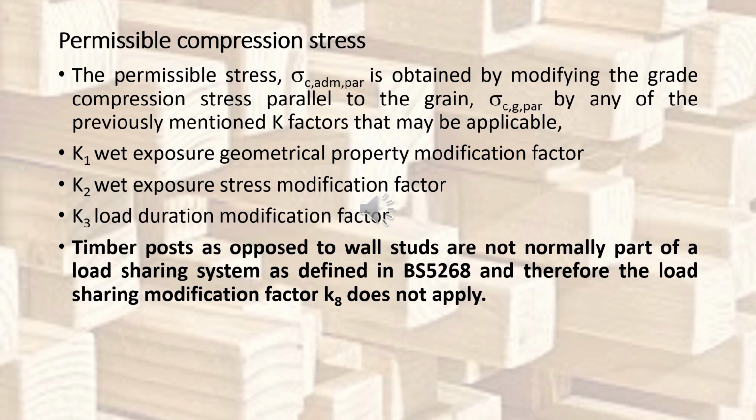Timber posts, as opposed to wall studs, are not normally part of a load sharing system as defined in British Standard 5268. Therefore, the load sharing modification factor K8 does not apply here.